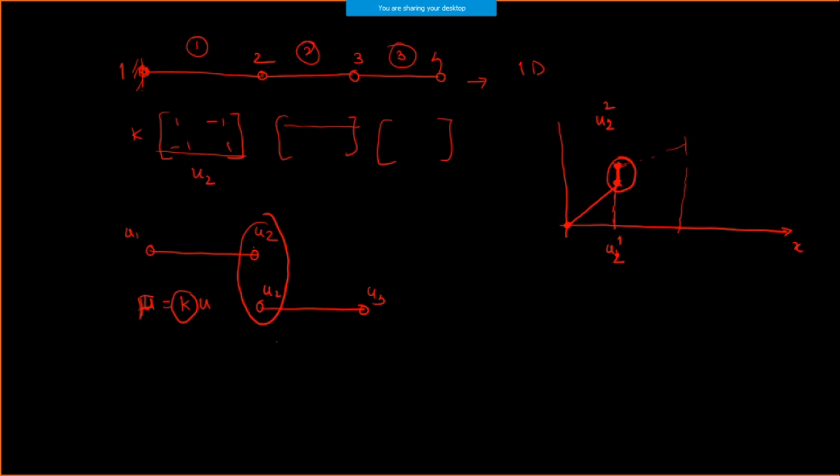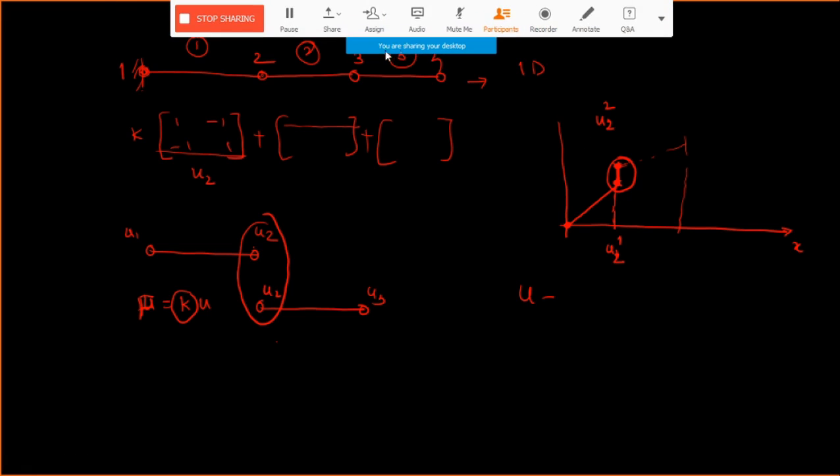So that is the reason these two should be the same, and that's why we add up all these equations and get an assembly. Wherever there are common nodes, the displacement of these nodes should be the same, or they should be added up. That is what you are doing in the first step. That is a C0 type of approximation, or convergence. Why is it called C0? U is my field variable.